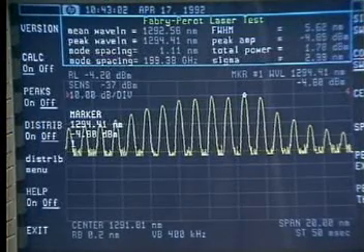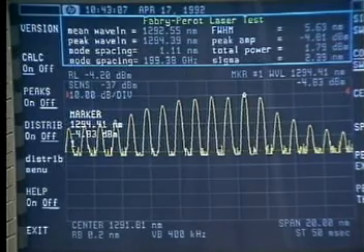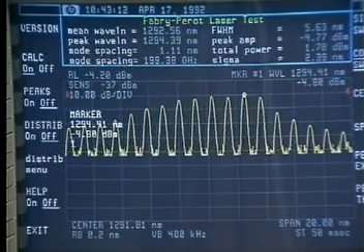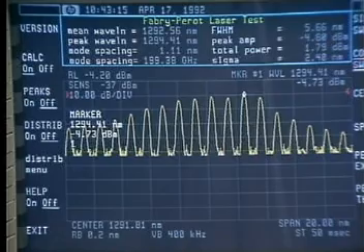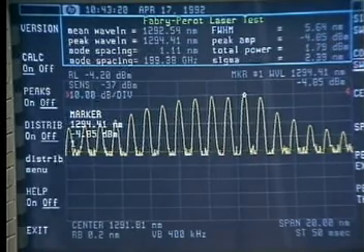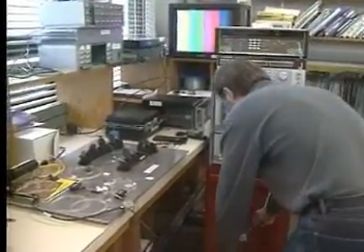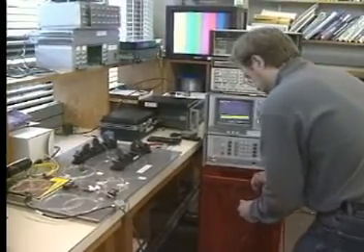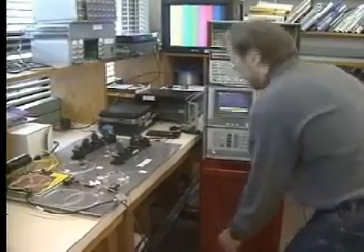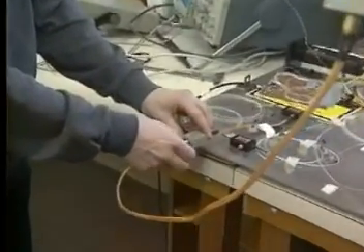Second, some of these photons of differing wavelength may trigger their own stimulated emission processes. This is like having a number of lasers of slightly different wavelength operating simultaneously. An optical spectrum analyzer shows these side modes on either side of the center wavelength of the laser. Both of these effects cause an increase in spectral width of the laser output that lowers the quality of the device. Because light of varying wavelengths travels through a fiber at different velocities, spectral width is the main limiting factor of high-speed single-mode systems operating over long distances.